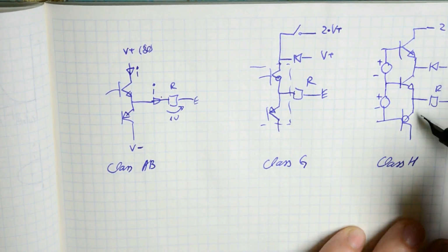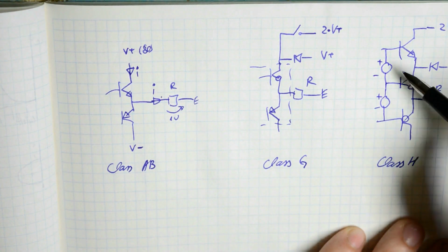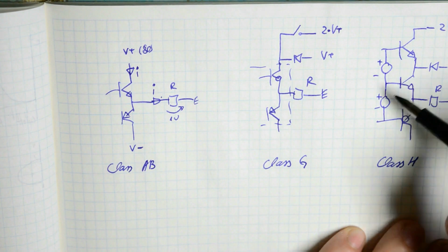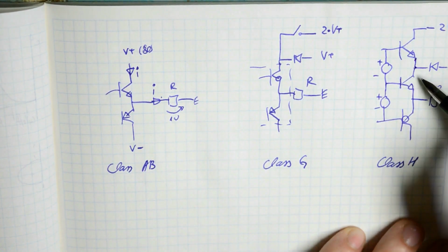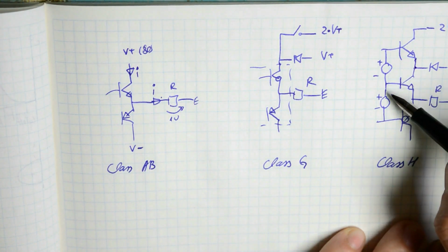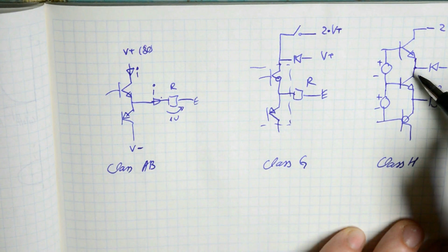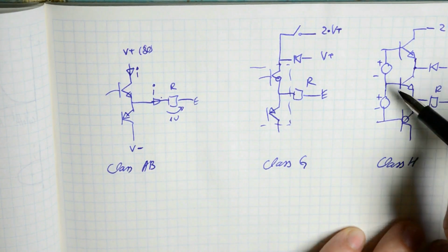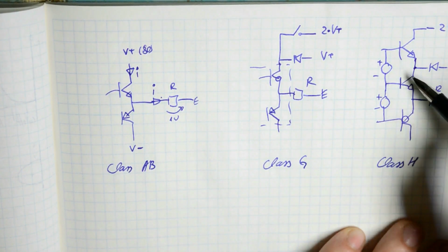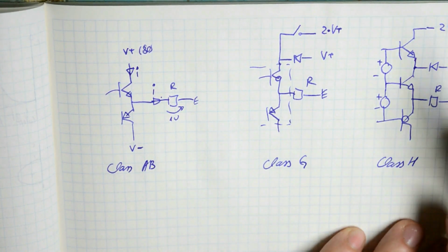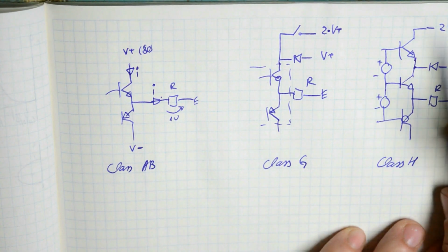the supply of the output stage, but rather you're building a linear supply whose output voltage varies in accordance to the input signal. So your output stage will only be supplied with a voltage that's the input signal plus a bit, so 1-2 volts. It will never jump directly from one voltage to the other. It will slowly increase and decrease according to the output requirement. This will give you much better linearity and much less noise on the output.